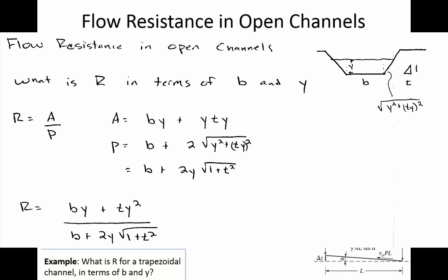All right. The wetted perimeter, though, is a little bit ugly because we've got this, this bottom is easy. That's going to be in the wetted perimeter. Wetted perimeter for an open channel doesn't include the top where it's touching the air. The perimeter of a pipe is just the physical perimeter of the pipe because the pipe is full of water all the way to the top. And so for a pipe, the perimeter is just going to be pi d. But for this, we're only going to include where the water is touching.